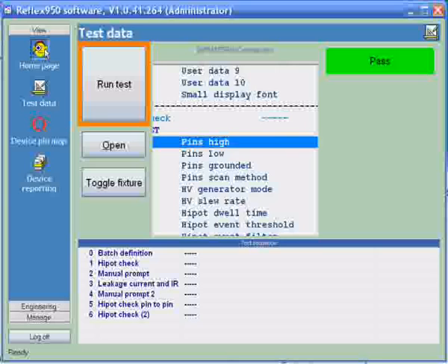150 to 155 high and pins 142 to 147 low, we can test them not only in an individual way. Here now we're going to test between every possible combination of these pins. You can see the activity of the tester here walking through all those combinations of the pins.